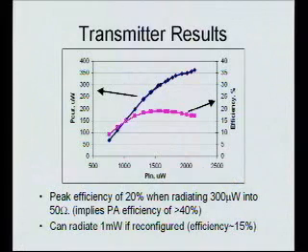Okay, and just proving that it works, I swept bias current to get P in, and then this is just a plot of that measured output power. You can see you can hit a pretty wide range, and the efficiency gets up to about 20%. That efficiency is actually the full radio, so that's the oscillator plus the dividers and things plus the output driver. So the output driver was more like 40 or 50% efficient, but then you have all the extra overheads.